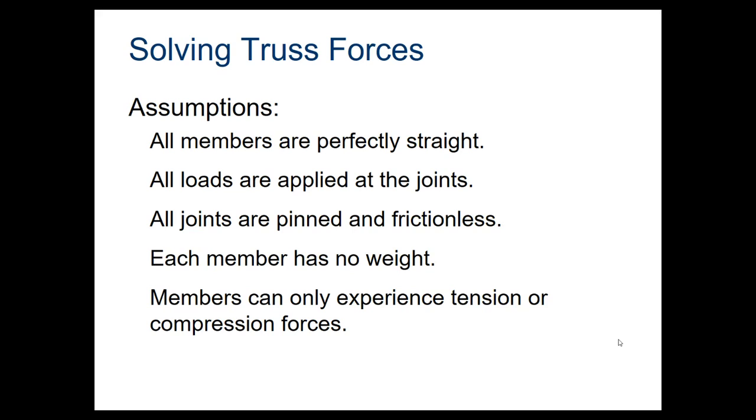Understanding that when you are designing things, you would also put in a safety factor and a margin of error. You would say, okay, if it is designed to withstand 100 pounds, then I can safely put, say, 50 on there. I'm not going to say, okay, I designed it for 100, so let's put 100 on there, because you really haven't accounted for any possible error that might be in there.